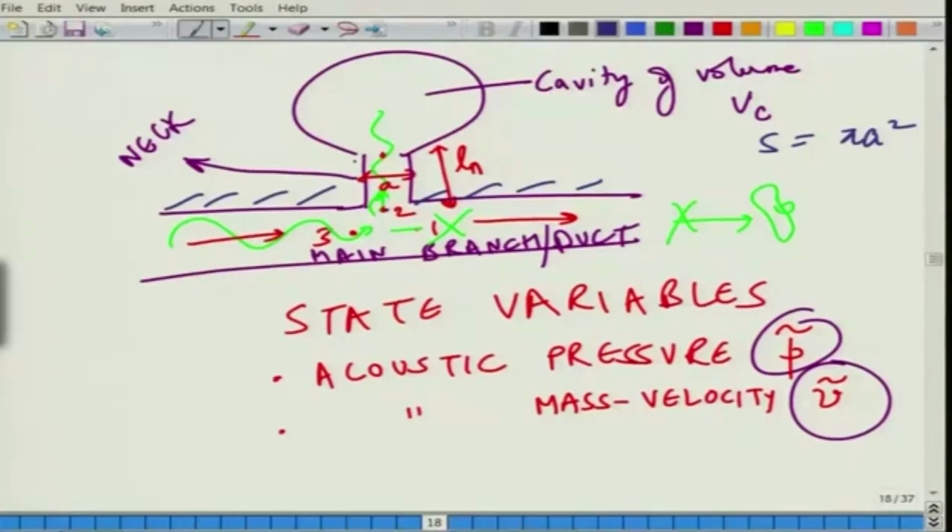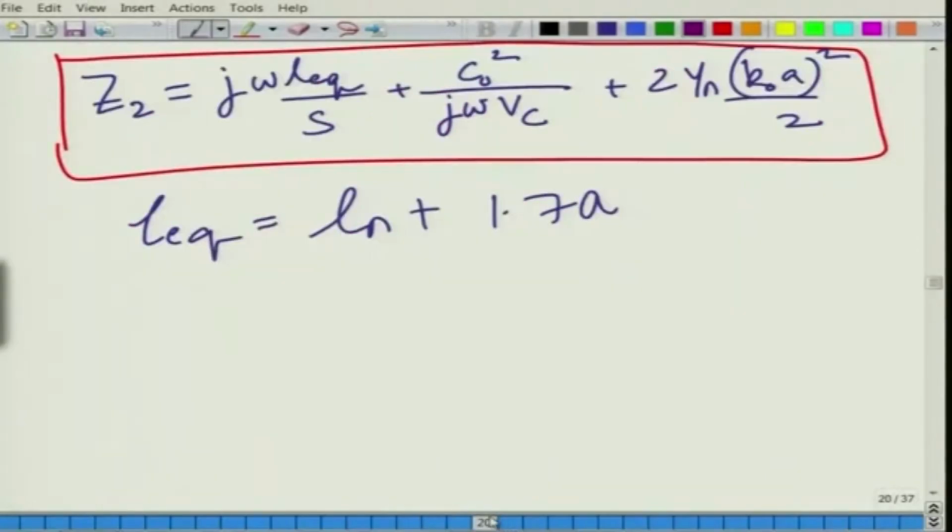So, this is your tube, it will definitely have some thickness, 1 mm, 2 mm, 3 mm, and this thickness is important not only from the acoustic end correction point of view, but also to enforce the structural rigidity so that the breakout noise is not there, otherwise it defeats the purpose. So, here you have your plus T or T wall, you can think of this.